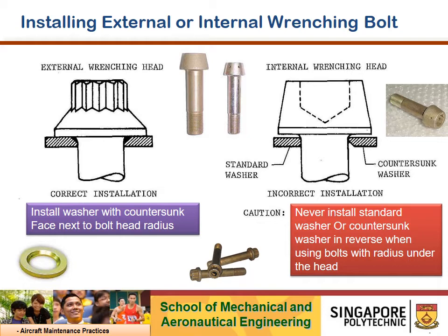External, you are turning it through the external hex head. The internal will be by Allen key. Do take note that we have to use a countersunk washer. Okay, this is a countersunk washer, and you make sure that when you install it, the countersunk is facing the manufacturer head where there's a radius fit in. There's a radius